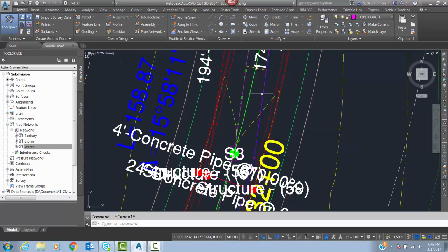When we set our elevations, we do it a little bit differently than the others, because we have to maintain that 7.5 foot down, but it doesn't matter if we're sloping downhill all the time because it's under pressure. So we can have uphill slopes, we can have downhill, we can have flat, it doesn't matter as long as we stay under that 7.5. And we want to hug that 7.5 line as close as we can, so we minimize the amount of stuff we have to cut out.